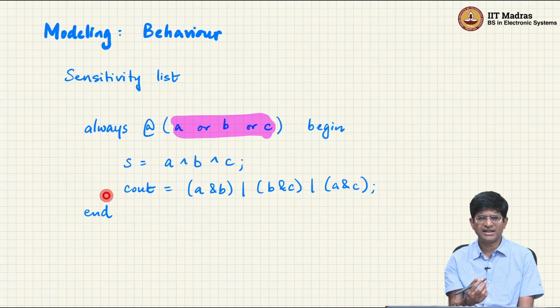You can use things like switch case statements in order to do really complex large multiplexers in some sense, right? Or state machine implementations. So always blocks or this kind of behavioral modeling is probably where the real power of the language lies, especially if you are trying to do large scale design.